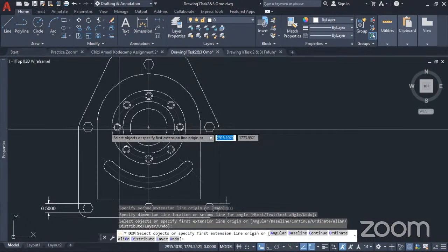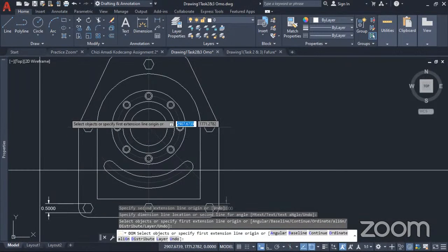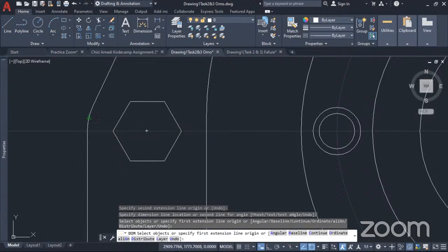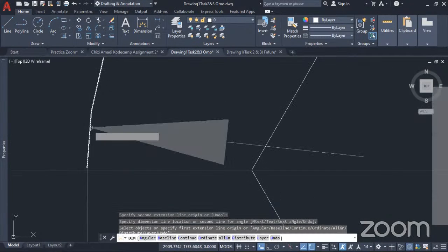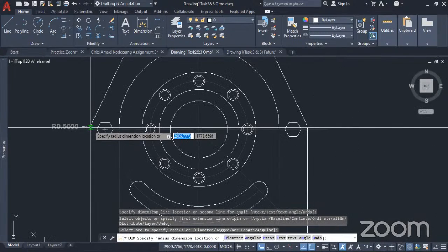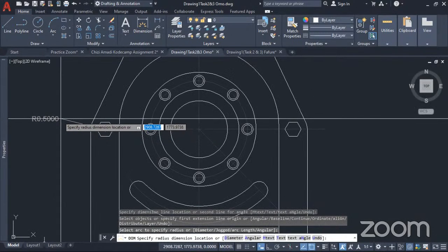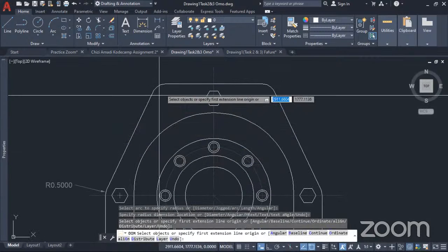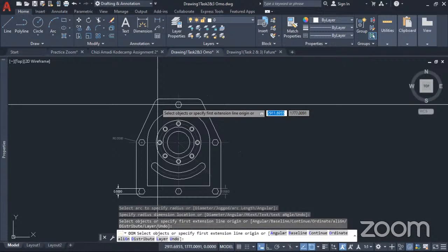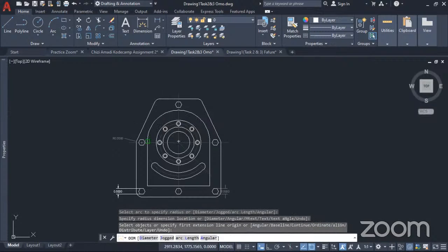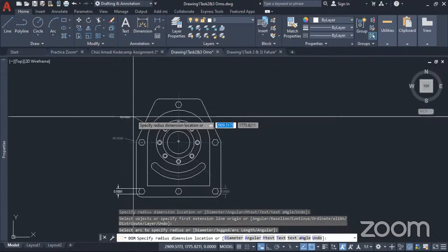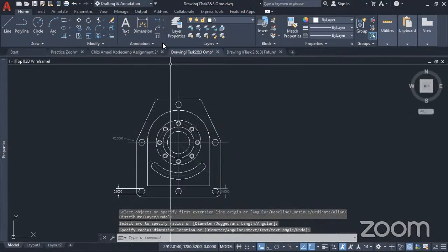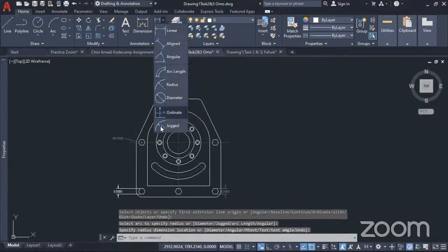So you can decide to do this. And then there's a fillet, there should be a fillet here. Select on this part of it and drag it like so, the way you want. There's also fillets here. Drag and keep going. But for this, I use the jog dimension. And you know what the jog dimension is.